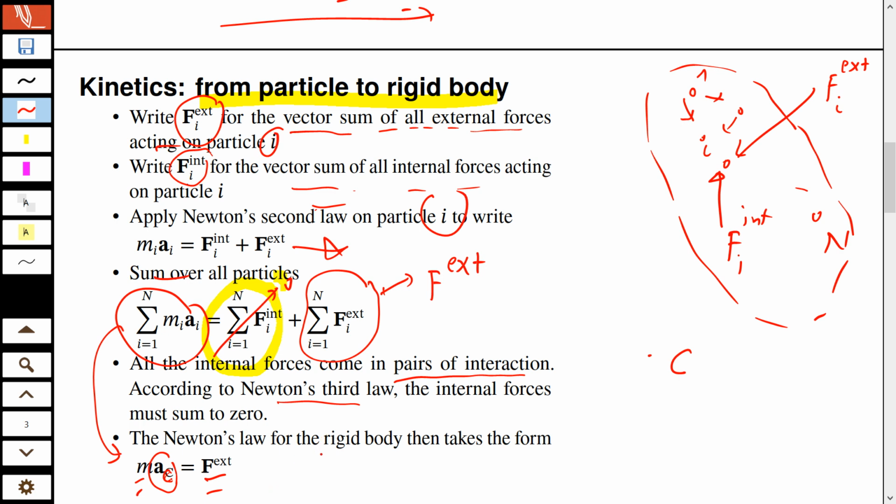One student in the other lecture asked me, why is this not zero? Because these forces also come in pairs. So how would you answer that? Why is this not zero? Anyone? Because those pairs will be made with particles outside the system, or bodies outside the system, and our system is this body. So we are writing an equation for this body. Even if this cancels out, that will be another equation, and if we increase the scope of our system to include those bodies, then it will be zero.